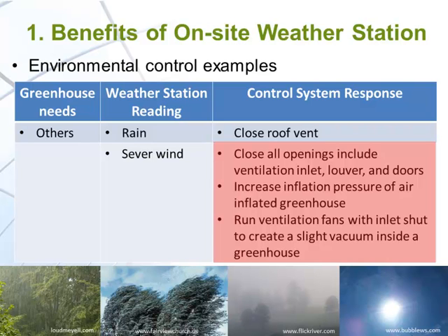Lastly, a negatively pressurized greenhouse can withstand strong wind better. Disconnect the arms of the motors on all ventilation inlet shutters and tape the shutters closed. Then turn on enough exhaust fans to create a vacuum in the greenhouse. This will suck the inner polyfilm tight against the frame, making the glazing material more wind resistant.